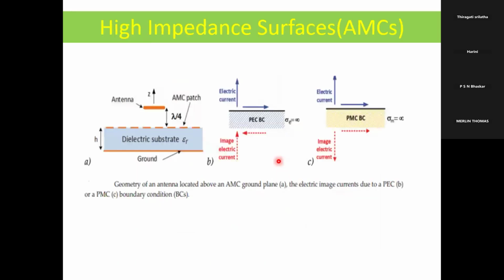Now there are other materials similar to metamaterials which have specific properties. As we mentioned, if you say a material is a metamaterial, you have to prove that by showing the values of mu and epsilon. If they are negative, it becomes double negative. If they're positive, it's a forward medium. Like that, if you want to classify any material as a metamaterial, you can do so by observing the values of mu and epsilon.